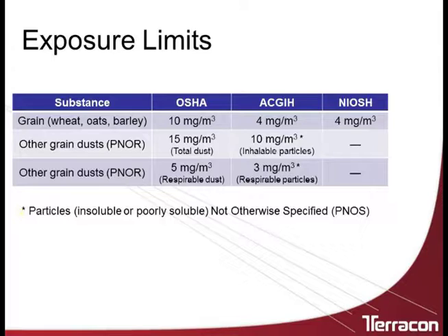However, if you are proactive in your program and you use ACGIH limits, you're going to be well below the PELs. And you'll be out ahead in the event that they change a PEL. Theirs are referred to as threshold limit values. And one of the interesting things here is because this is a registered trademark, when OSHA adopted these, they had to come up with a different name. That's how you came up with PEL.